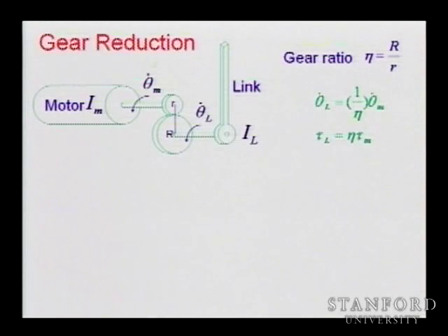if the gear ratio is 1, basically you have direct drive, and you need a big motor to produce a torque, right? But this big motor is heavy, and with the robot, putting a heavy motor here is a problem. So what do we do? We put higher and higher gear ratio, reducing the size of the motor. And we can achieve the torque because we are using a high gear ratio.